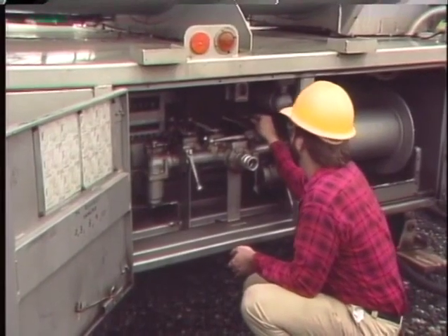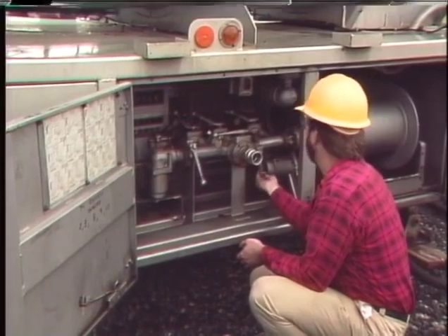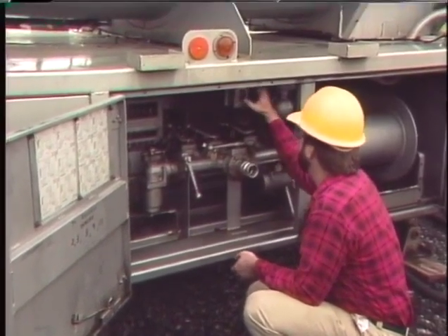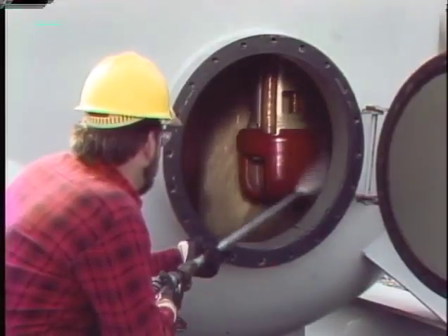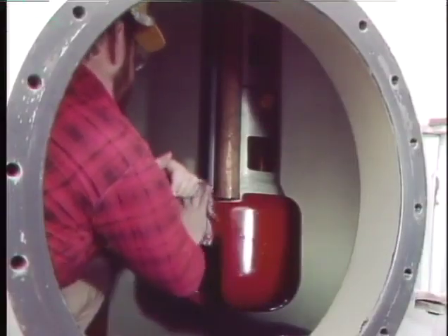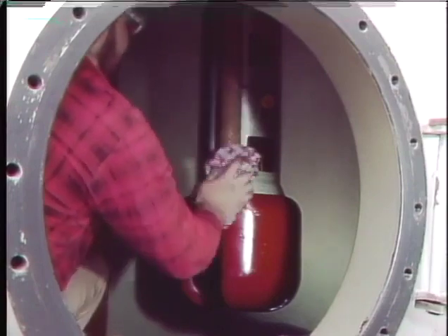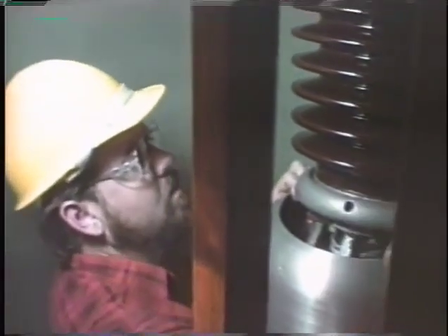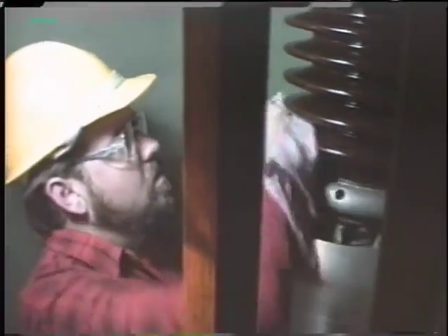The internal breaker mechanisms may be coated with dirty oil and carbon, so they are usually rinsed off with clean oil by reversing the direction of oil flow through the pump and spraying the inside of the breaker. Then the internal components can be wiped off with a clean, lint-free rag to remove any dirt that didn't rinse off. Solvents are generally not used because they attract moisture as they evaporate, and moisture affects the dielectric strength of the oil and insulating parts.